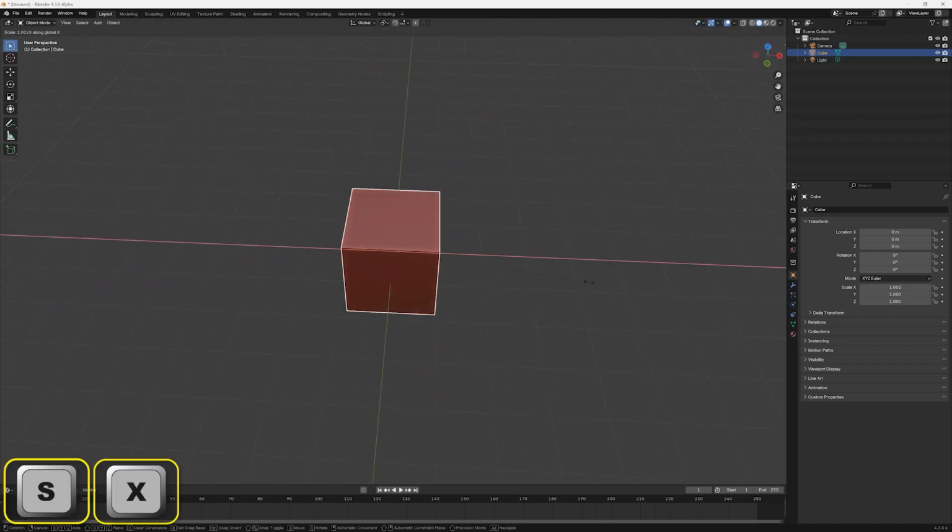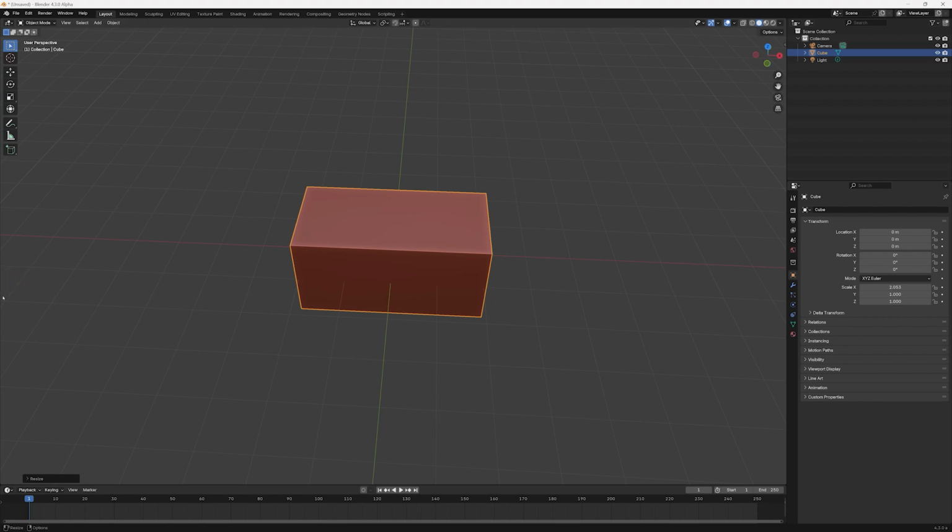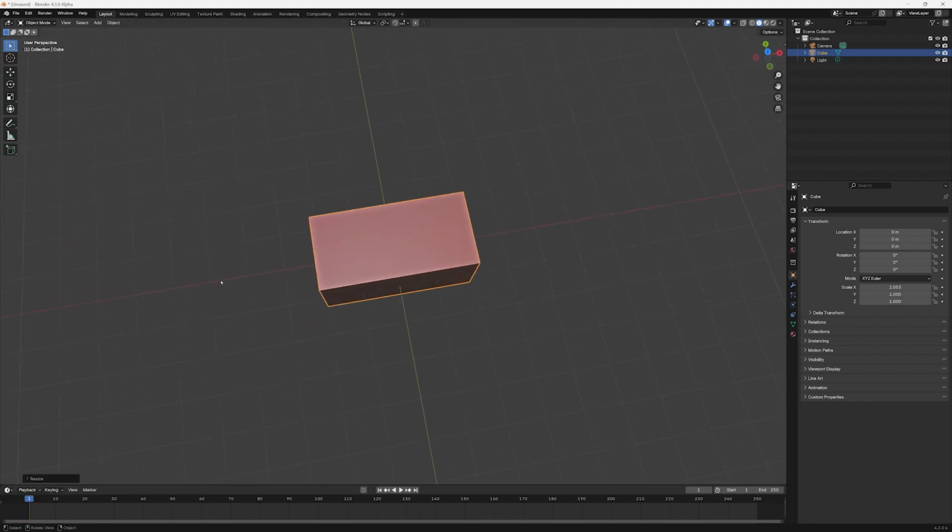Before we go any further, we need to bring up the importance of applying scale when we've resized an object, since using the Inset tool is one of the situations where we are going to run into problems if we've forgotten to do that when a mesh's shape has been modified.